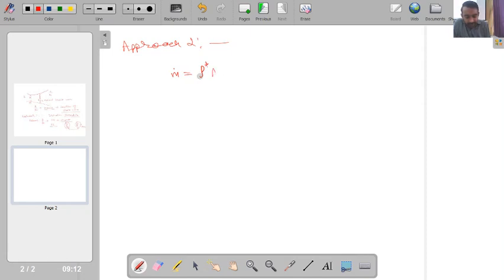So rho star, A star, and V star. Okay, so I can even write this as rho star, A star, and small a star. Okay, considering that at this Mach number V star will be equal to a star. Okay, now we know that a normal shock wave will come only when we have a choked flow situation. Okay, because ultimately what happens in the case of a choked flow situation is that our pressures are in between the pressure required for isentropic subsonic-supersonic flow and completely isentropic subsonic flow.